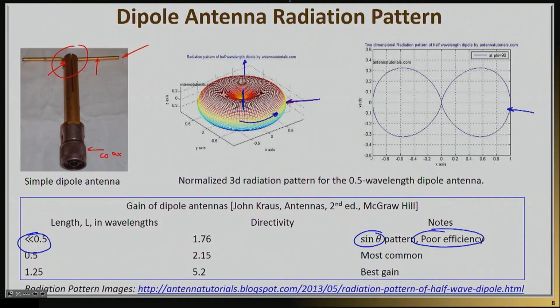For example, if you have an AM radio operating at kilohertz, you can't really get much of a half wavelength antenna there. Obviously, at kilohertz, such a thing would be humongous. So you're simply stuck with a small dipole, and you simply transmit a lot of power, and you work with an antenna that is very, very poor in terms of efficiency.